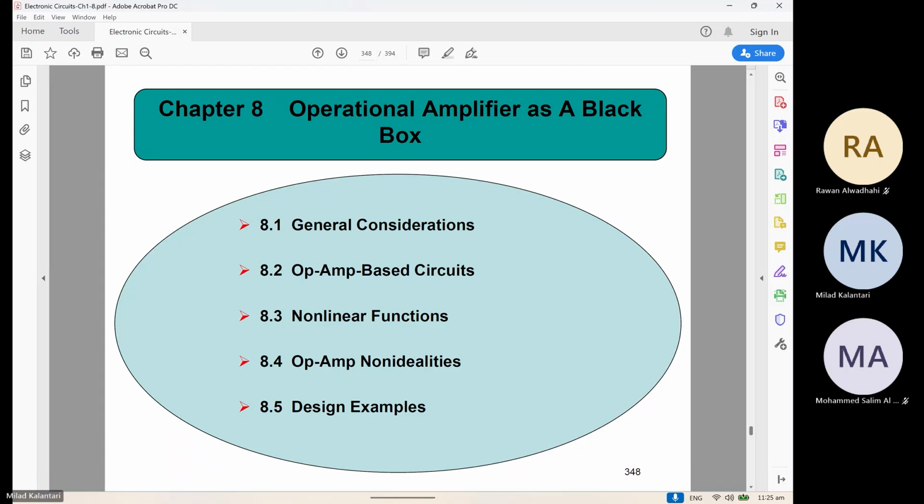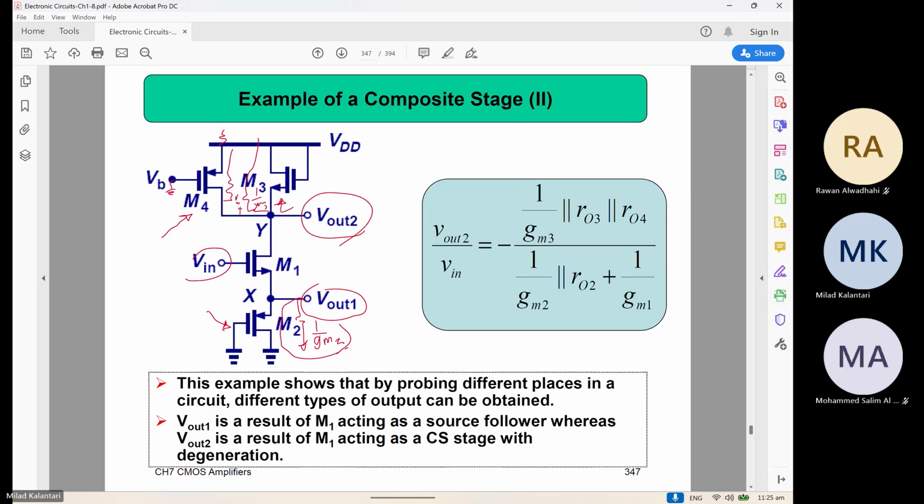So I guess this is enough for the MOSFET, but you need to do more practice to figure out the biasing, calculating the GM values and the device sizes, a little bit different than the BJT, because in the BJT, whatever you need to know was only the collector current, right?